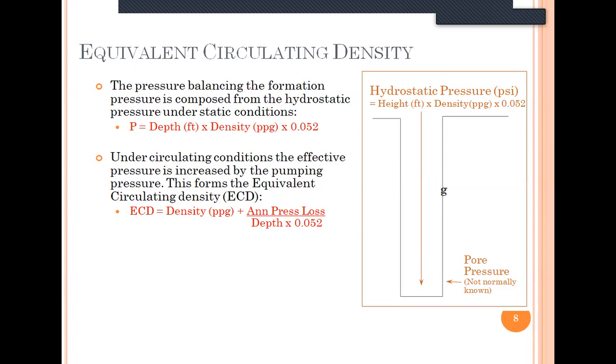Okay, so we can increase the annular velocity. Again, you will have a high ECD. Okay, I will increase the RPM and dilute the annulus with cuttings. Hey man, you will increase the ECD again. So all the time you are thinking about the ECD, because your mud weight you can control from the surface, you can increase or reduce it. But the ECD is affected by a lot of factors: the cuttings load in the annulus, the density of your mud, the design of your BHA. All of this affects the ECD.